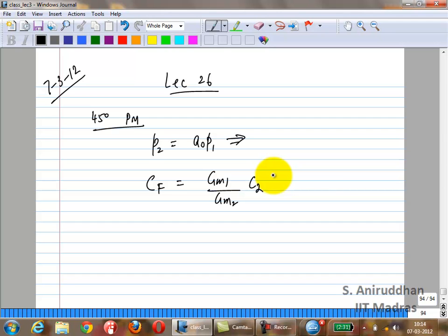Now suppose, we also talked right at the end of class yesterday about setting RF not only equal to 1 over GM2, but even larger. If we set RF much larger than 1 over GM2, what happens? So it goes all the way to infinity, comes back, wraps around and starts moving back. Correct? So at some point of time what you can do is, the other thing which some people proposed was cancelling.